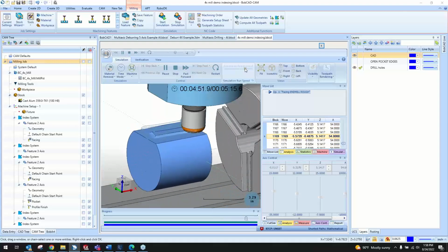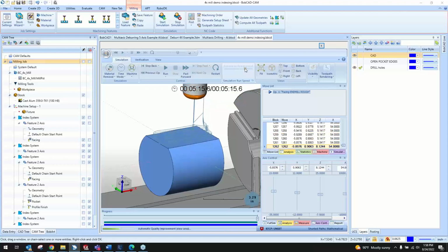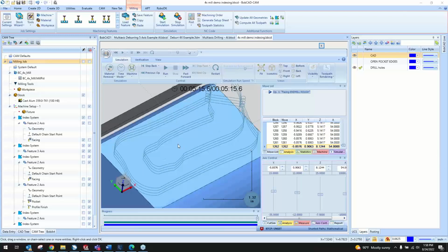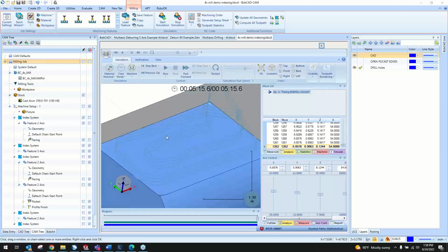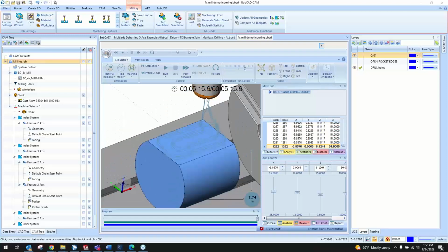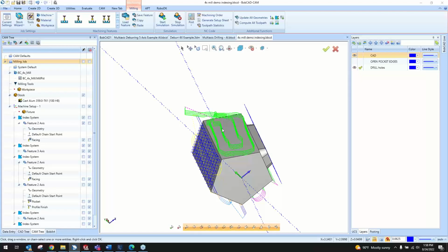Yeah, so we used to have an issue where it used to leave an island in the center there. I don't know if that's what you are referring to there, Stephen. But with version 34, our newest build, it has resolved that issue. Now everything kind of overlaps there so that it doesn't leave anything in the center. Let me know if there's any issues that you have with the part file, or send it over to us and we can take a look at that. If it's with a chamfer tool or something like that, it may be different than the corner radius I'm thinking of here.